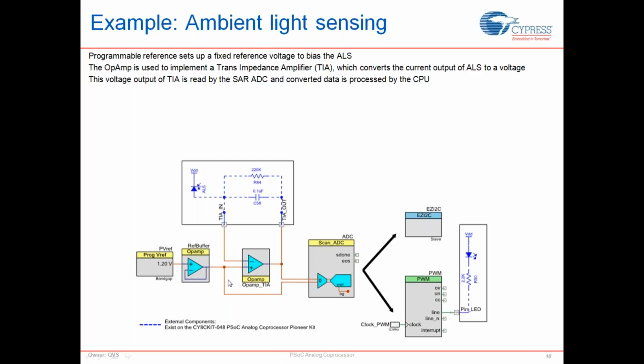For this, what you use is a transimpedance amplifier. What the transimpedance amplifier does is it takes a current input and converts it into a voltage output. The basic implementation of a transimpedance amplifier has a feedback resistor that provides negative feedback into your amplifier circuit. What that effectively does is maintain the non-inverting input's voltage plus the offset at the inverting input. So hence you have the bias now set up for the sensor.